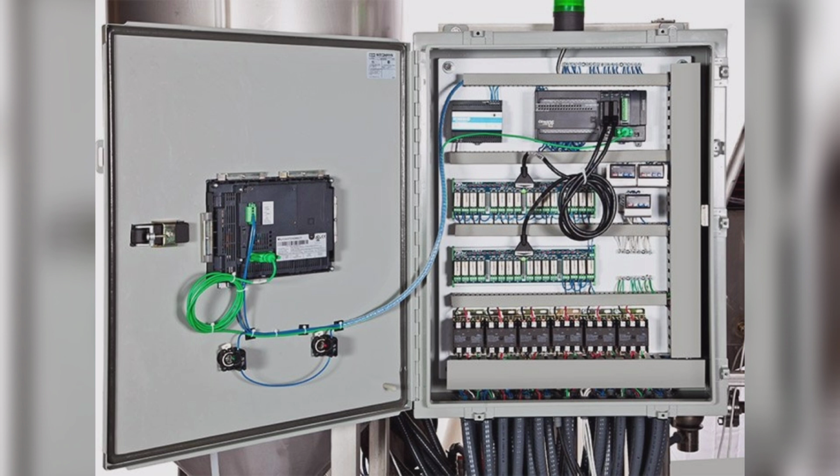The next component is a surge arrestor. After the power comes into the panel from the main circuit breaker, it runs into the surge arrestor. A surge arrestor is a device that protects all the electrical equipment inside the control panel from electrical surges or overvoltage. An electrical surge can come from a lightning strike or utility power surges as well.